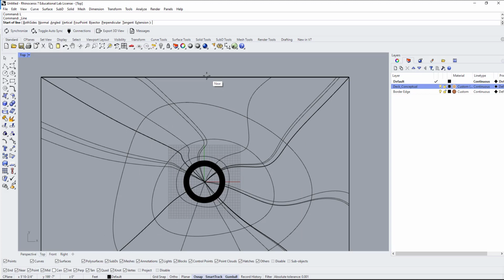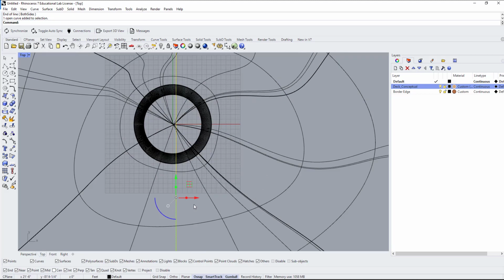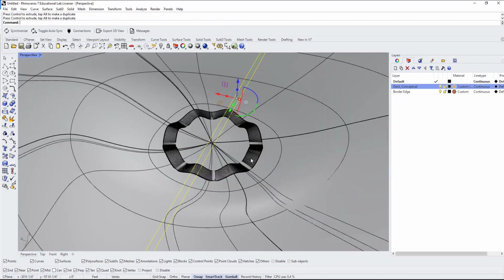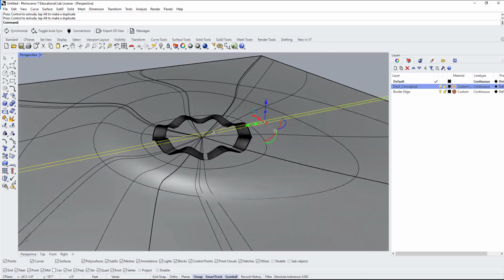After I have created the site, it's important to have some diagrammatic expressions for our design rationale. So I will create an intersection of roads at the center of this circular play structure. So I am creating two lines, one offset from another. I will now rotate this set of lines by 90 degrees.